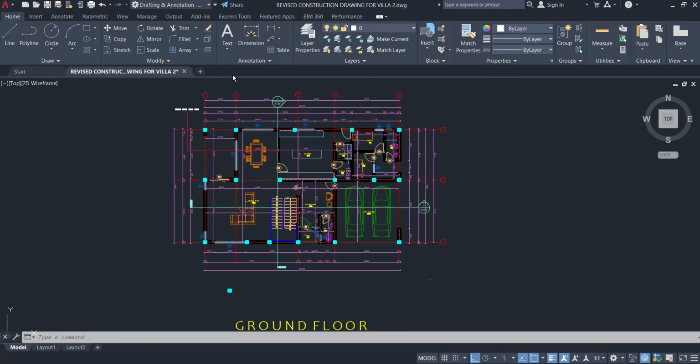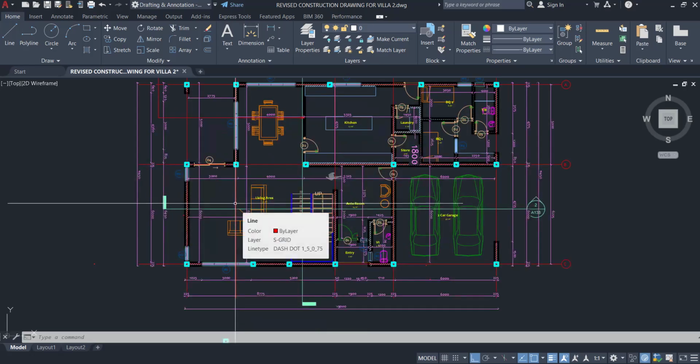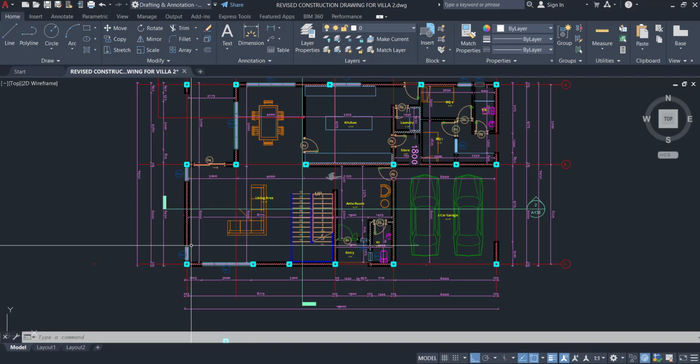So if I want to do that, I will have to break all these vertical members between grid line B and C, all the beams there that are around 6.2. You break it so that it will now leave around 3 meters. If you want to use 16 mm bars for beam and column, you should make sure your span is not more than 4 to 4.5 meters, so that if you provide 3Y16 or the reinforcement required, you can do 3 at the top, then put 2 supporting it. I hope you get it. So let's leave the columns like this.